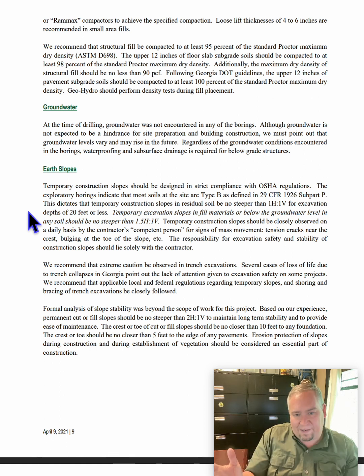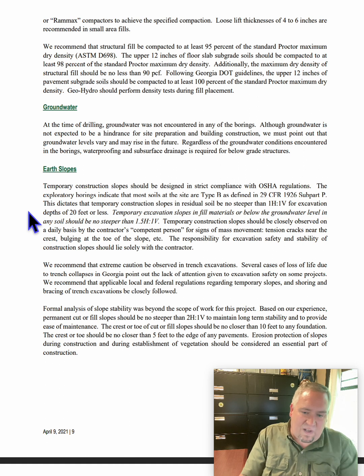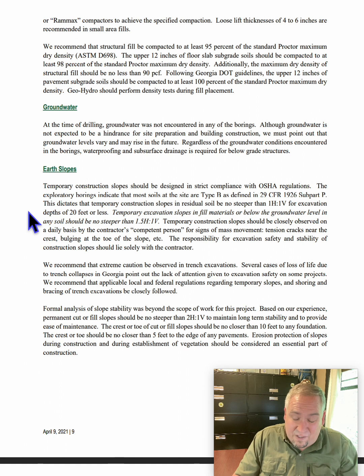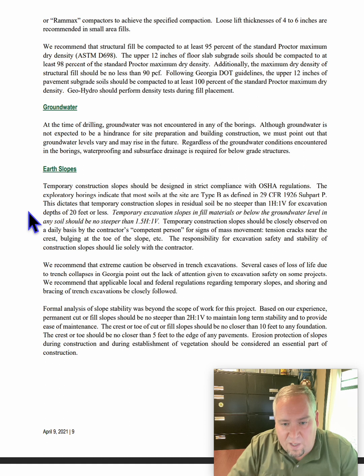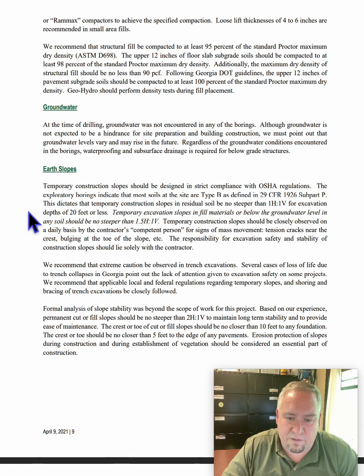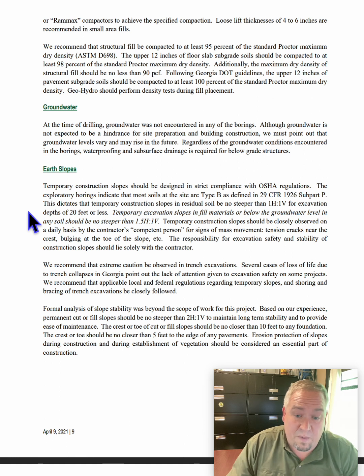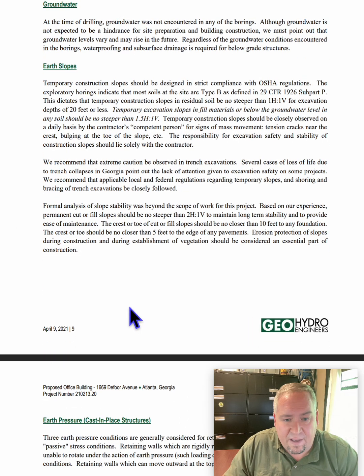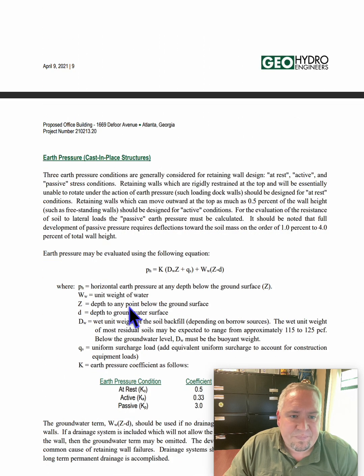So if you're laying it back for pipe, the geotech's there and says, hey man, I know soils, and this soil, you're going to have to lay it back a little more because it's going to slough on you. Or this soil here, for this wall, you're wanting to do your cutout and you're hitting your limits of disturbance, you can actually steepen that wall up and you're going to be okay. But you've had a registered professional talk to you about that soil, so we don't want to take on that risk and liability. Bring in the team, bring in the meeting of the minds, and everybody look at it and determine what's going to be best for the project, keeping guys safe and keeping the soil stabilized.